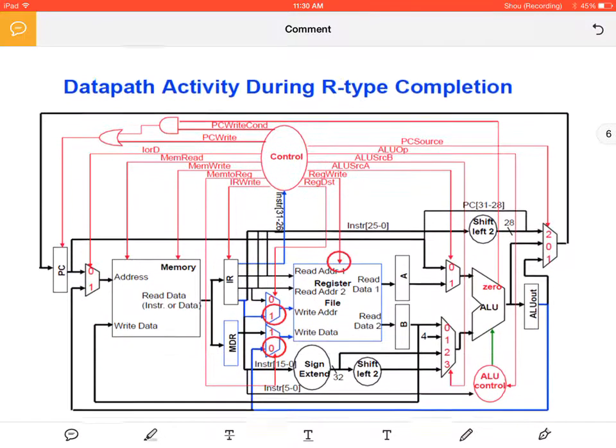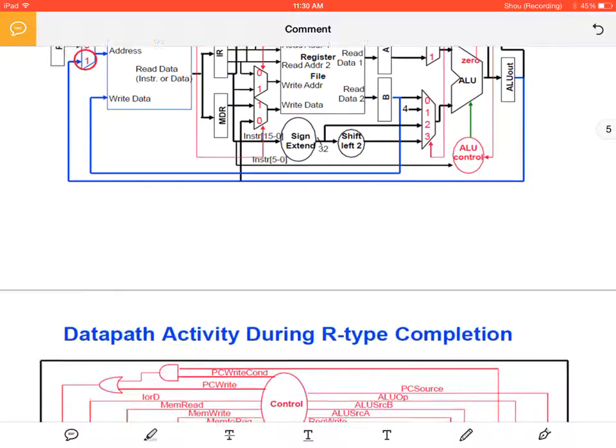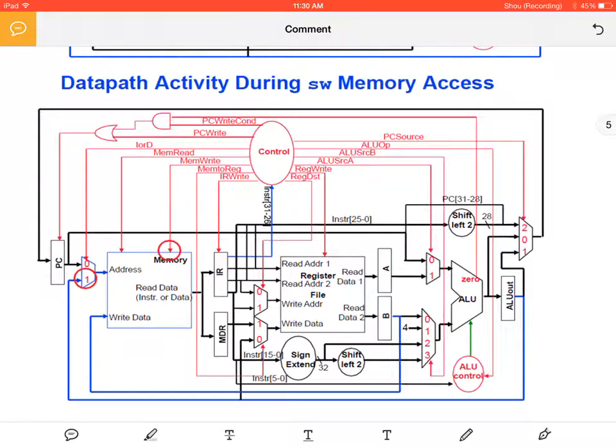And now for R-type instructions, now we have, oh yes, Thomas. Are we not checking for hazards? Okay, this is also a very good question. The control signals are what's taking care of the hazards. Okay. So by setting value for memory to 0, mem to reg at 0 if we want to do it, as we design the finite state machine, by setting these specific values to 0 and 1, it eliminates those hazards.